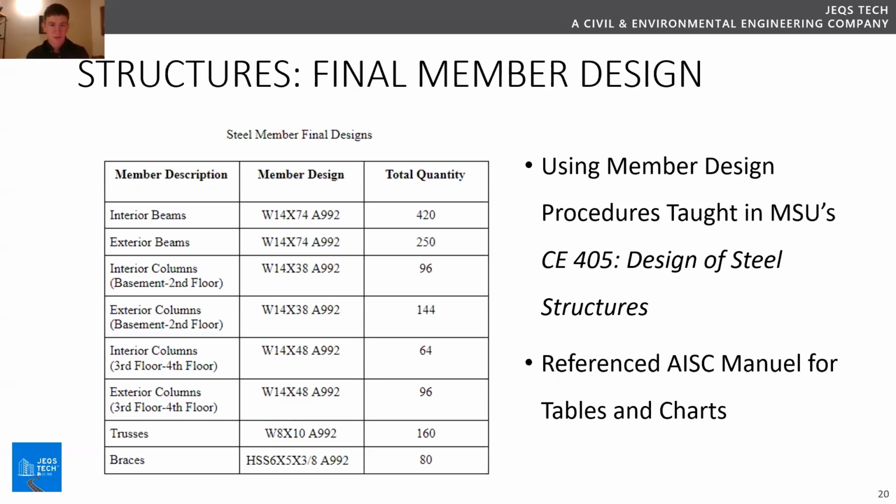It's important to point out that the max forces were used in design. Specifically for columns, there was such a difference between the lower columns and the upper columns that subcategories were made. But generally, we tried to group them all together to keep the construction simple and economical.